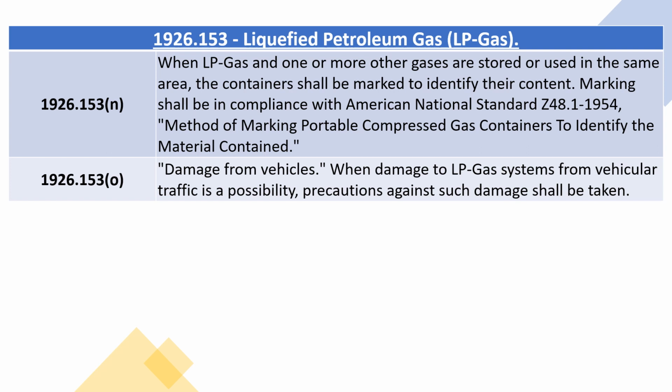1926.153(n) When LP gas and one or more other gases are stored or used in the same area, the containers shall be marked to identify their content. Marking shall be in compliance with American National Standard Z48.1-1954, Method of Marking Portable Compressed Gas Containers to Identify the Material Contained.